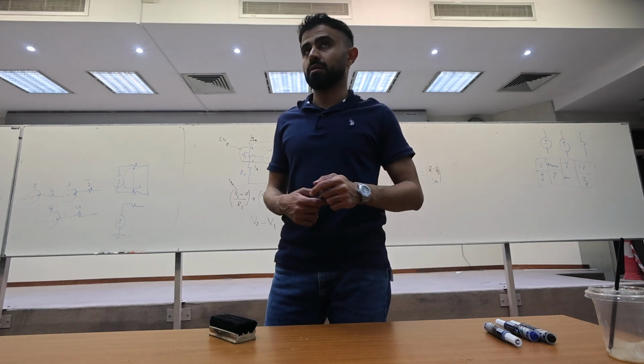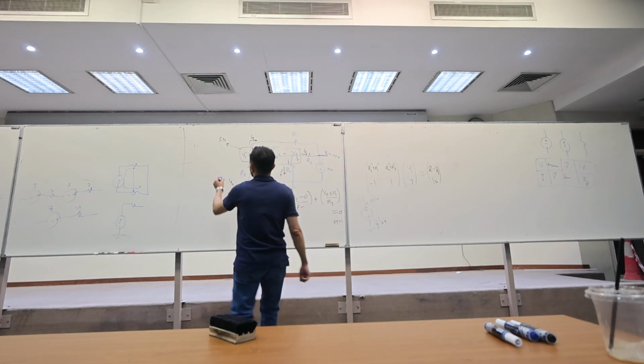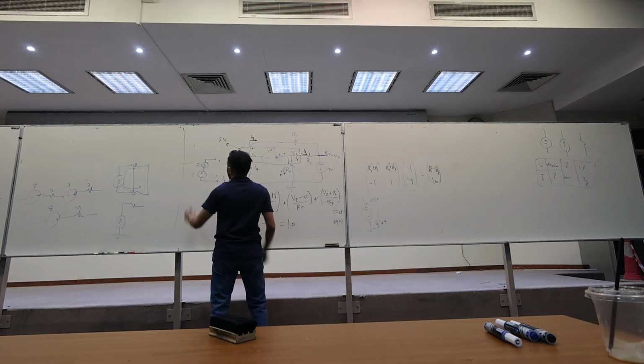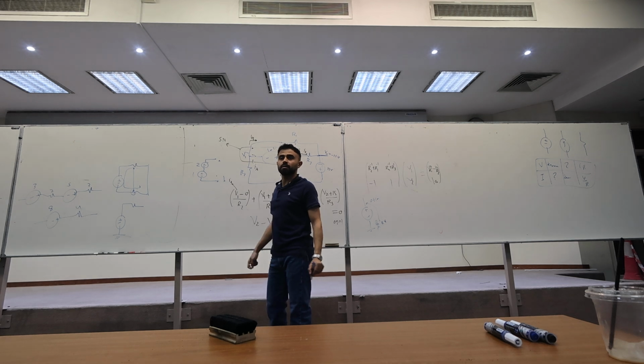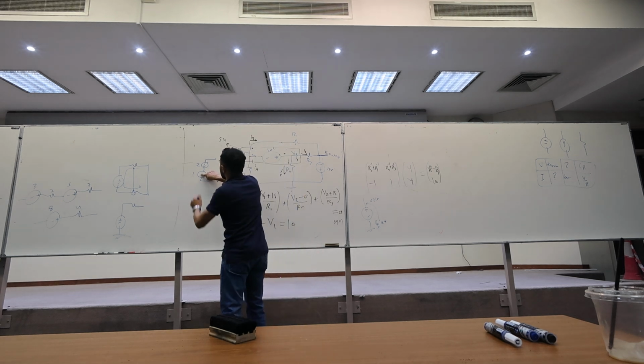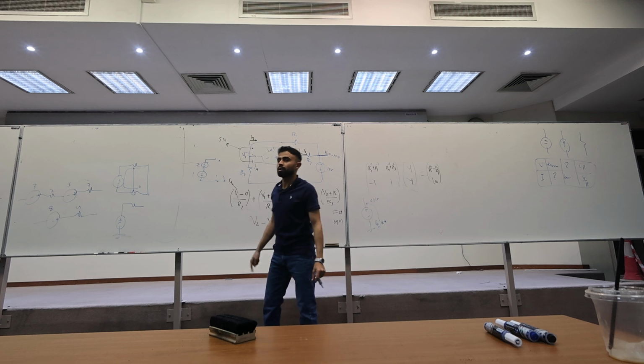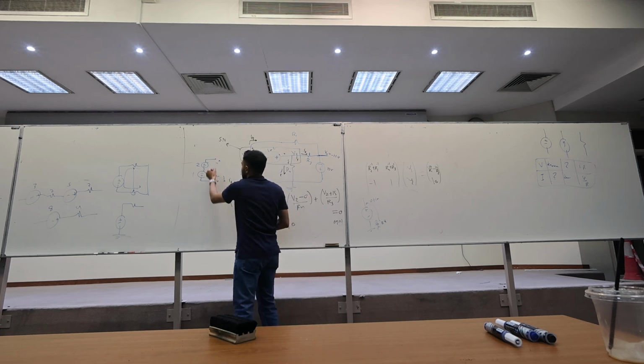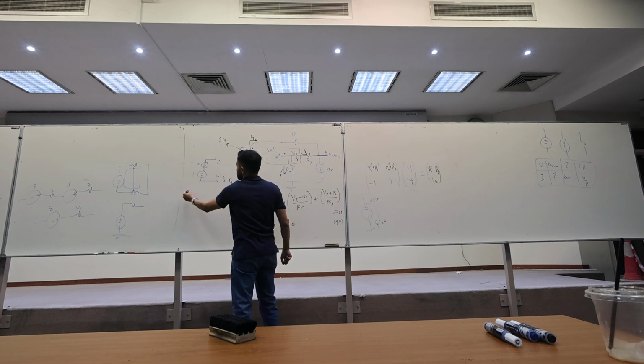If I bring you a question tomorrow on Thursday, what is the voltage drop across AB? 2 and 1. What is the voltage drop across AB? 3. Okay, what if I put minus and plus? Minus 1. Again, do the KVL. Voltage rise, voltage drop. Minus VAB minus 1 plus 2 equals 0. So VAB equals 1.